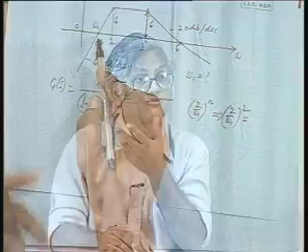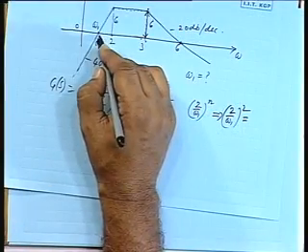If I go from 2 to 1, there is a jump of 12 dB. Alright. So 2 to what value, if I go, I will have a jump of 6? It's the geometric mean of 2 and 1, is it not? So you are in the middle, in the logarithmic scale. Equal distance means basically it is a ratio, it's a geometric mean. So it will be root 2 times less, that means 1 by root 2 of 2. So it will be root 2, 1.41. Okay.